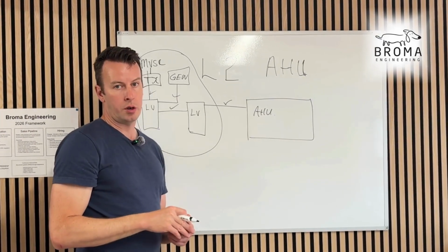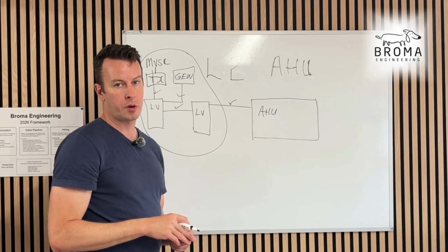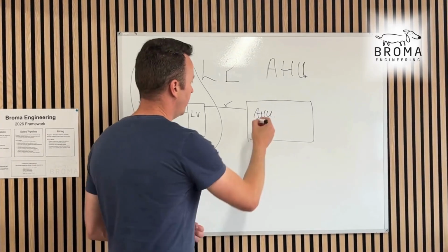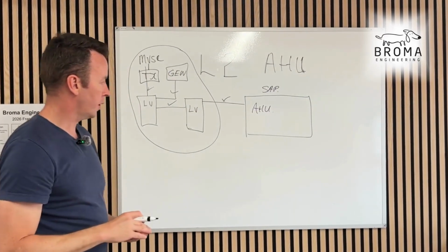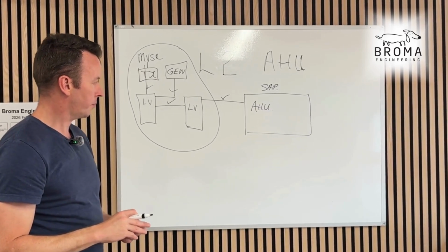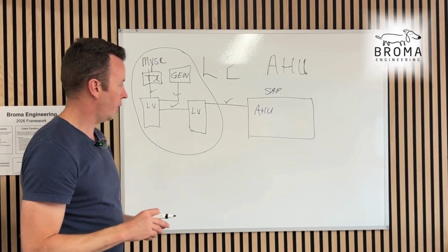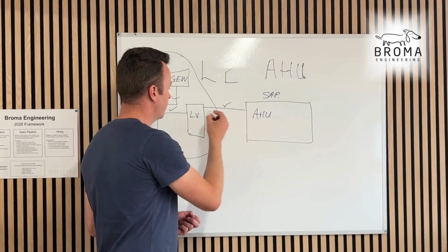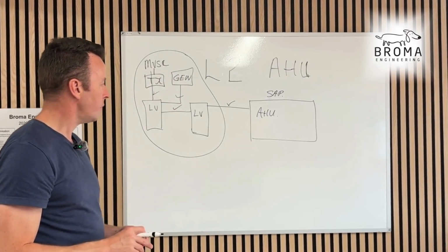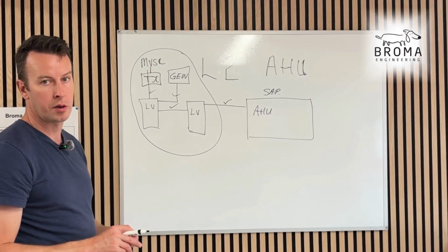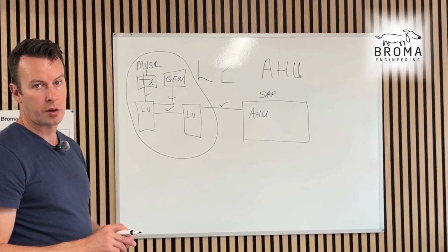So your senior appointed people, your SAP and your APs, are going to have to be involved in scheduling, understand this, what needs to be done, be there for the walk down, lockout, tagout. There'll have to be locks on the switchgear upstream, locks on the AHU if needed, locks on anything that can cause harm to anyone.